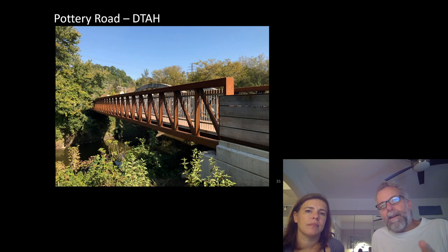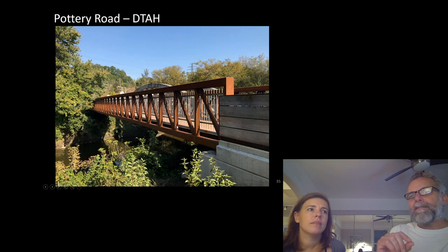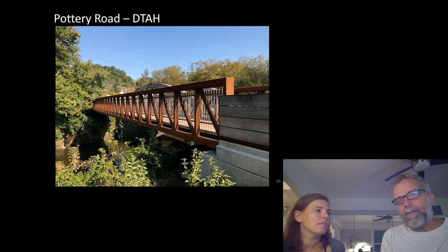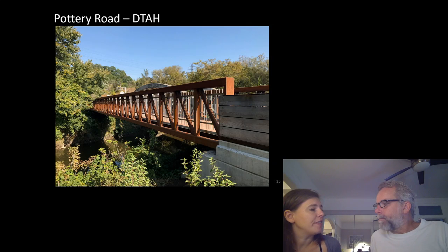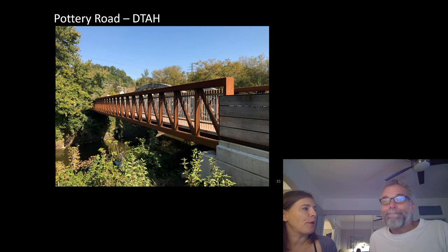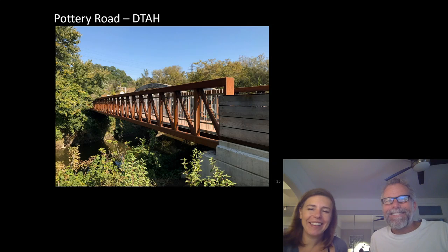The reason is that in an exposed environment, the HSS, if all the welds are fully sealed welds, presents the minimal surface area relative to cross-sectional area, so they stand up very well. It's a high longevity. And as I've discovered, they mass purchase 3 or 4 major sizes and keep them in stock in their shop or in their backyard.